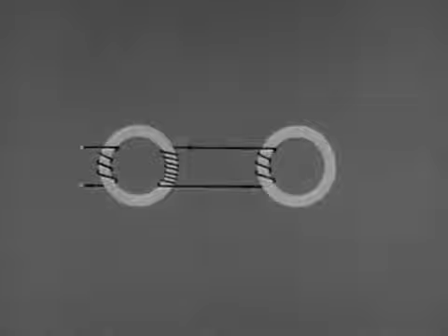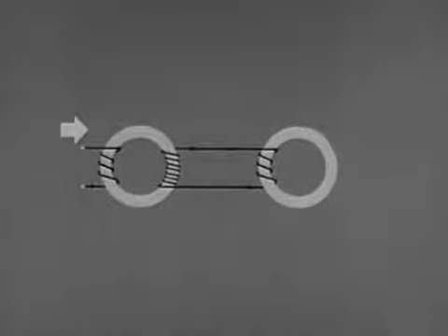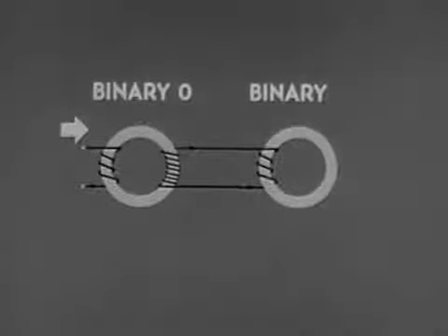In a typical core circuit, current flows in only one direction, into the input of the first core. We'll take the non-dot side for our example. We'll assume that, initially, the left core is set to 0 and the right core to 1. All we want to do is store a binary 1 in the left core. Watch what happens with the circuit as we have it.